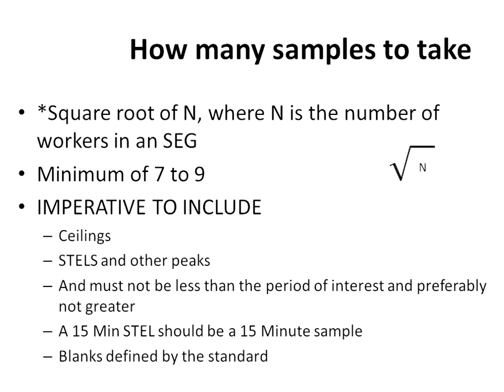And it's easy to do in a sense if you have 4 samples per worker. 4 samples times 4 workers is 16 samples. It's easy to get up above the minimum number of samples. It's much harder if you only have 2 workers. And then in your samples, remember to always include your STELs.